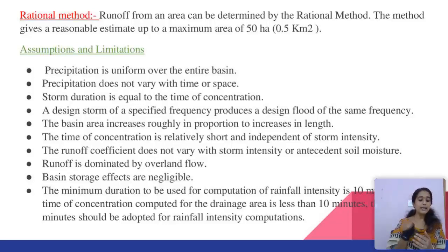Then the basin area increases roughly in proportion to the increase in length. That is, the length of the sewage system, that is the sewer pipelines, will increase in proportion with the increase in area. Then time of concentration is relatively short and independent of storm intensity. That is, TOC is relatively short, independent of storm intensity. And then the runoff coefficient does not vary with the storm intensity or antecedent soil moisture.